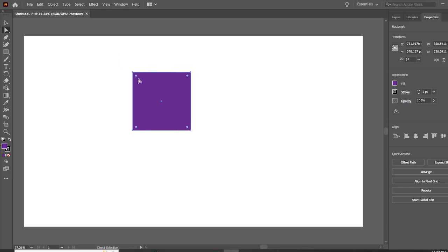I can take it back. Okay, let's say I just want to round just 2 of these corners here. I'm just going to click on one. Now come over here and hold my shift and click on this. Then the next thing is left click and drag, so I can drag just these 2 at a time.